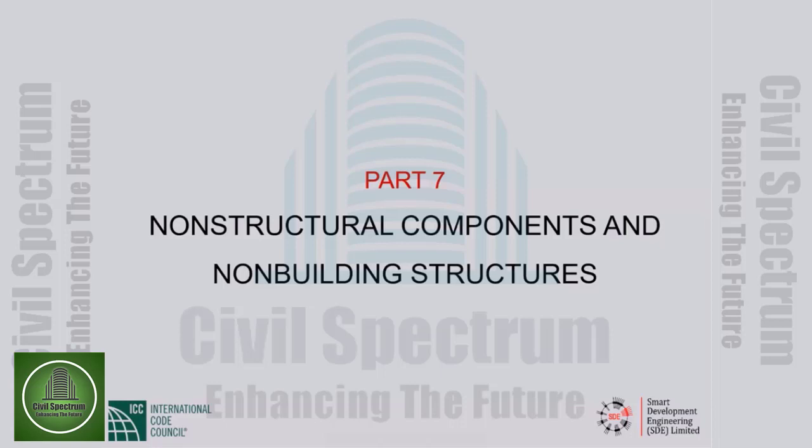I know what you are asking, but I did say that the interstory drift limits under non-earthquake forces do not make a lot of sense to me, particularly because the limits are in terms of building height rather than story height. So I find it difficult to take them seriously.